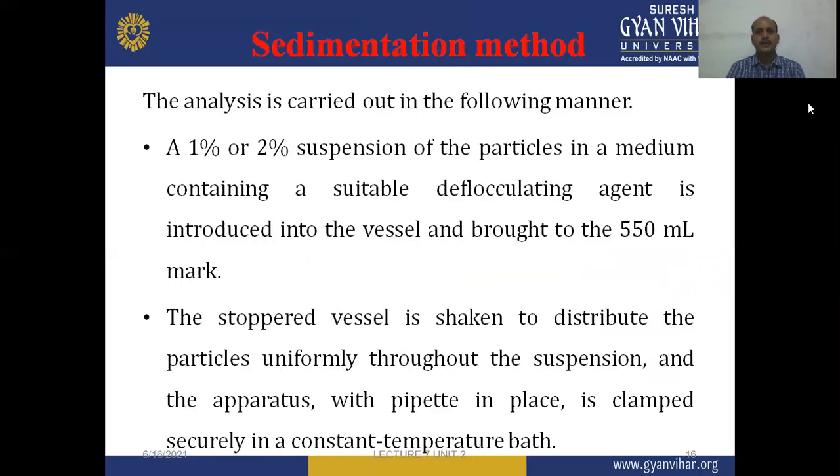Now, sedimentation method or procedure. The analysis is carried out in the following manner. First of all, a 1% or 2% weight by volume suspension of the particles in a medium containing a suitable deflocculating agent is introduced into the vessel and brought to the 550 ml mark. So, as we discussed, we have to use a deflocculating agent which can be helpful to segregate the particles or which can prevent the aggregation of different particles.